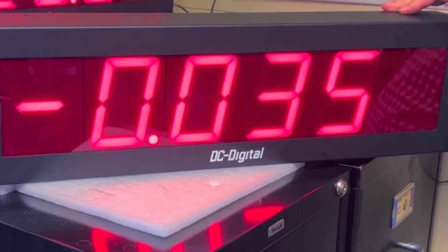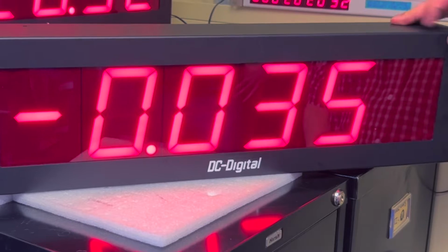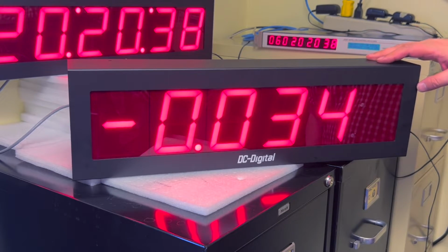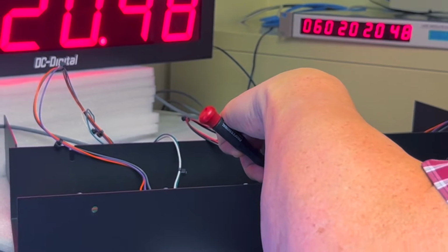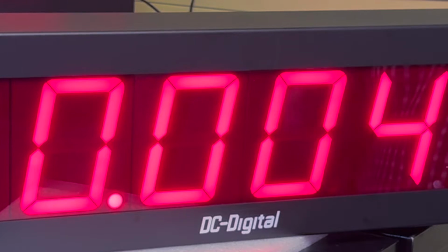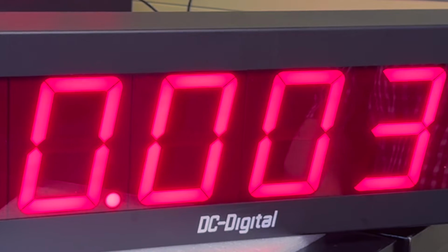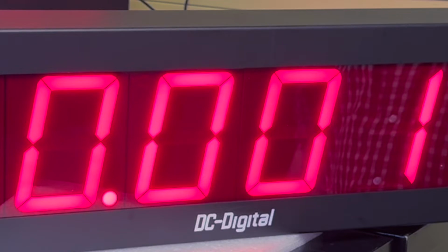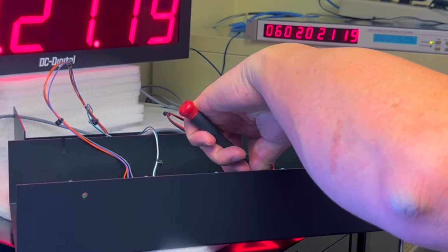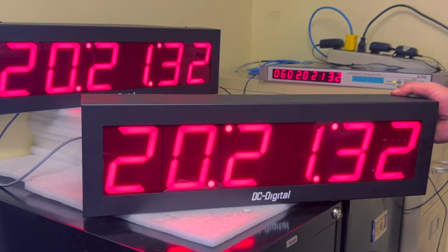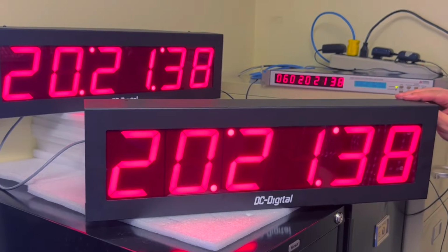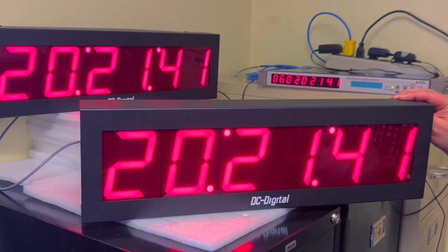Position 2 is our frequency deviation. And so frequency deviation, we are under 60 Hertz by 0.036 Hertz. Time deviation, and this is how close to UTC the system time is. So the system time is now ahead of UTC by this number of seconds. Now we're right on, and now we're behind. This is showing now the UTC time, which is the same as this time here, and it updates exactly in sync with the master clock.